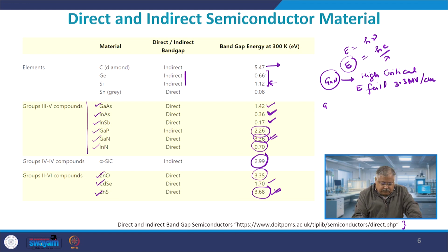If you look very carefully at GaN power devices, they have very low on-resistances, and therefore the currents are relatively high, and it also provides very low losses. Conduction losses are very, very low. Not only that, but they have a good saturation velocity.